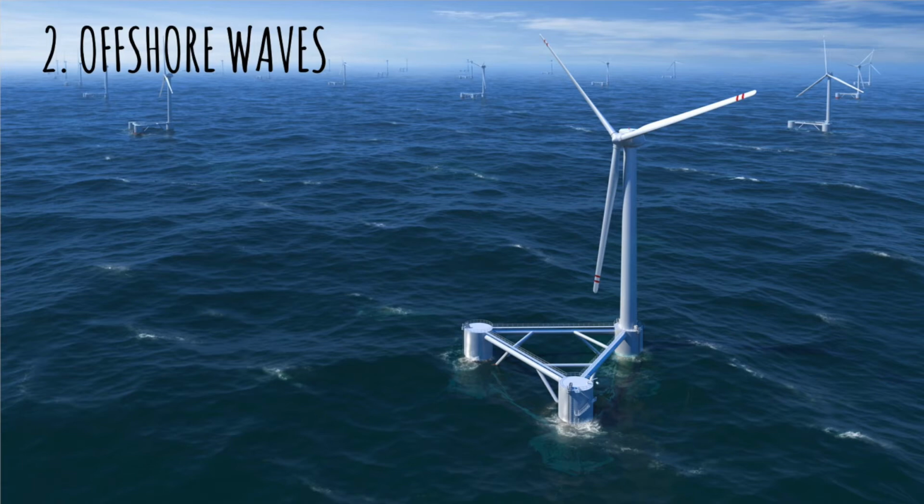As the swell passes underneath the device, one tube will move upward and the tube that it is connected to will move downward. This movement is repeated down the tubes as the wave passes underneath. The hinges between the tubes are connected to a pump. This pumps oil through a hydraulic motor as the tubes move, which in turn generates electricity as it spins around. This electricity generated can be taken to land via cables attached to the seabed.